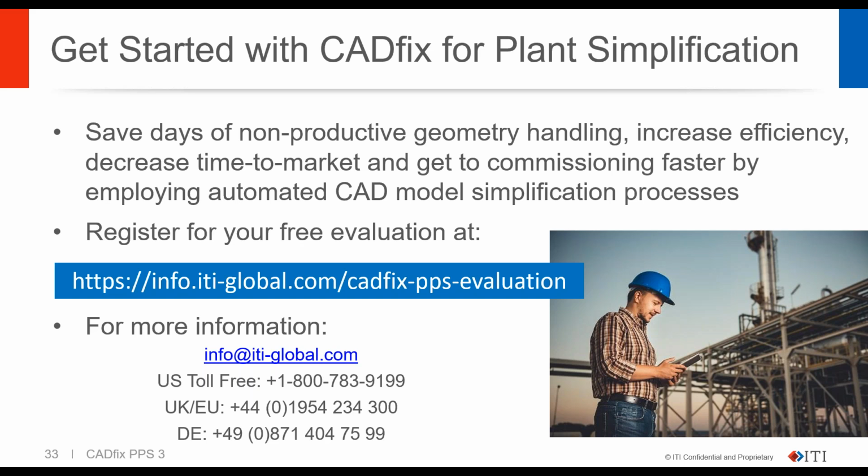In terms of what data is lost, well, you keep the original model, so you're never going to lose anything permanently. In terms of control over what's being simplified, as we just covered, we have the retainable keep list. But the changes to the model aren't permanent. You have your model and you can process it. You can select which tools you want to use, or you can process interactively. And there is quite a lot of control over the simplification process. And then you can save that out at the end as a new model.